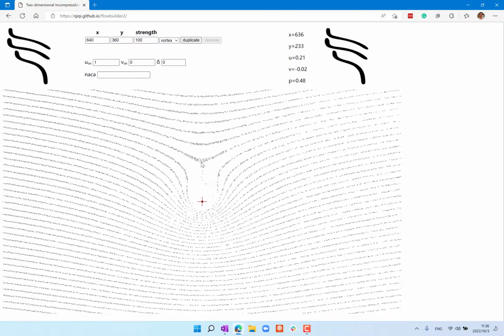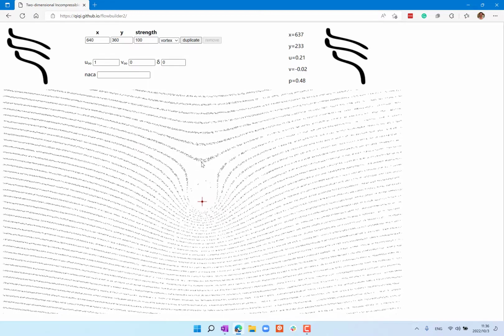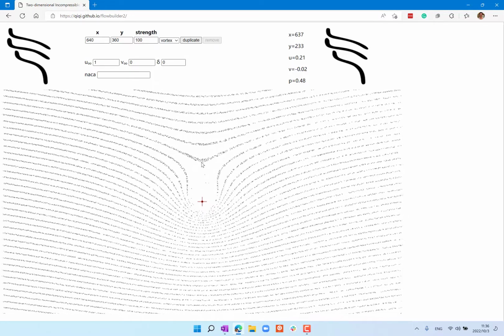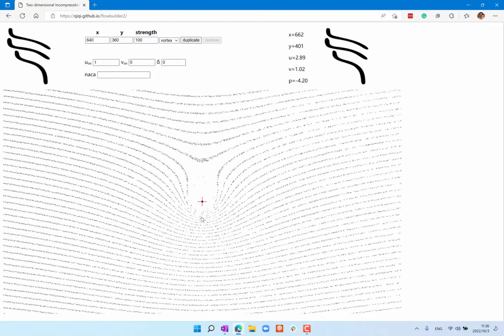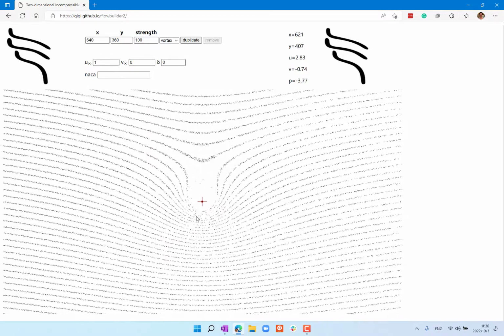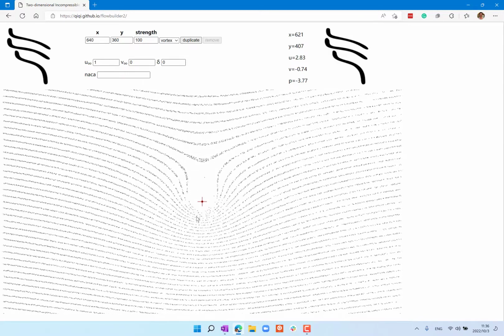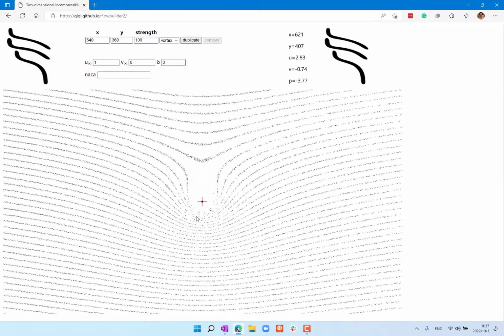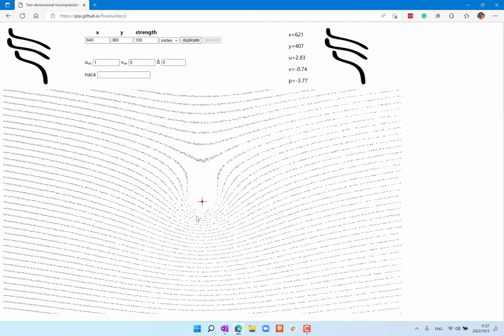Because U infinity is equal to 1 here. So P equal to 0.5 would be the flow decelerating to a complete standstill, right? So here it's pretty close. And over here the pressure is very low, so you get really high suction, right, downward. That's lift, right? Because the free stream goes that direction, and force perpendicular to the relative direction of motion is lift.